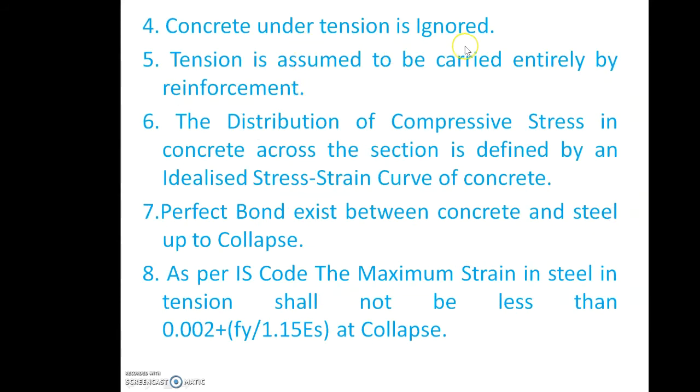Concrete under tension is ignored. In this case, we are assuming that the total tension is taken by the steel and the total compression is taken by the concrete itself. The distribution of compressive stress in concrete across the section is defined by an ideal stress strain curve of concrete. I will show it in the next slide.